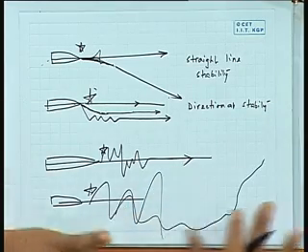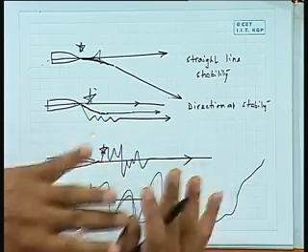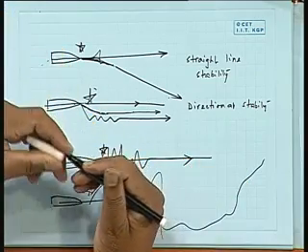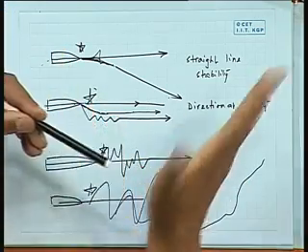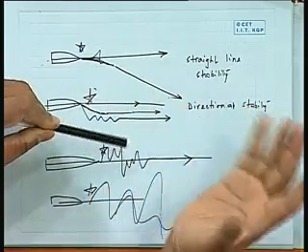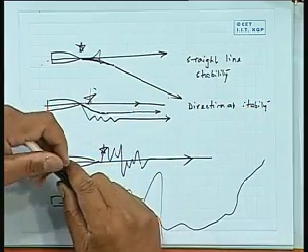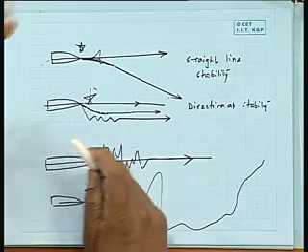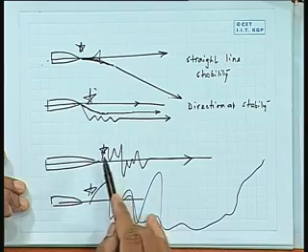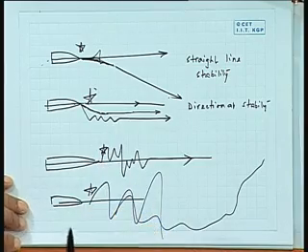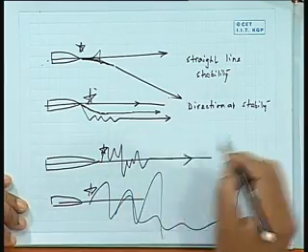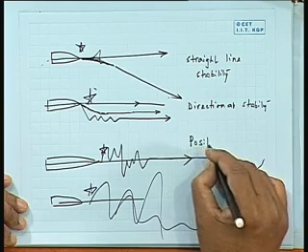We are not talking of that. I am talking of the definition of various kinds of stability that a ship can have. Instability is obviously when a disturbance is given, you remove that, it simply goes wherever, you have no control, then it is unstable. That is obvious, so I am not discussing that right now. Now, supposing it is stable, what kind of stability the ship may possess is the question. So, it can possess like this, it can possess like this, it can possess like this. Now I tell you that this can be called positional stability.